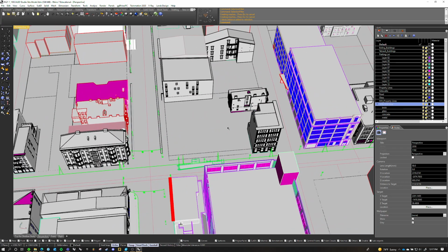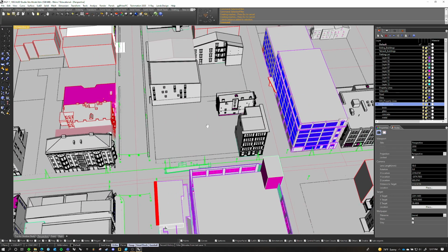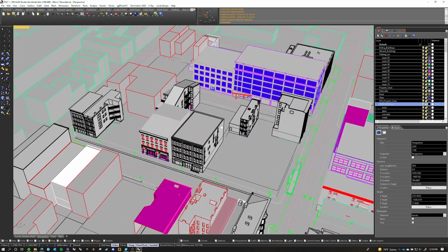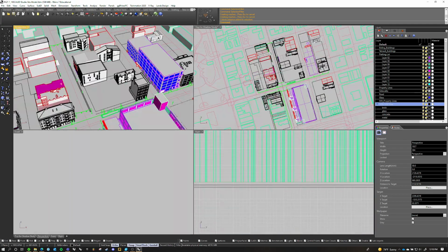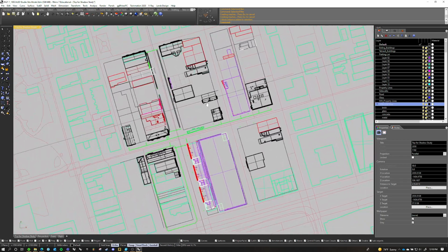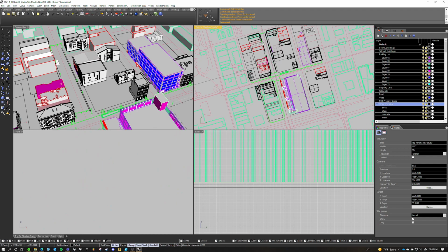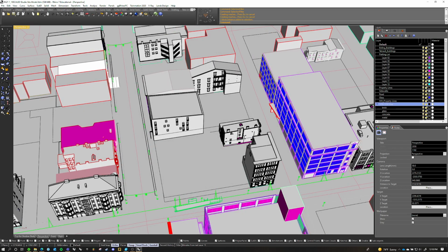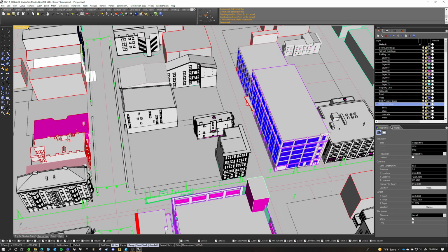And if you hold shift and right click, then it'll pan across the model. Panning is default in top view. You can't hold shift and then rotate or something. It's always just going to pan because you're locked in two dimensions.